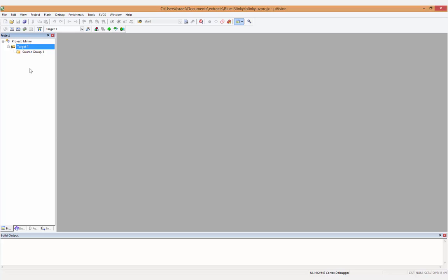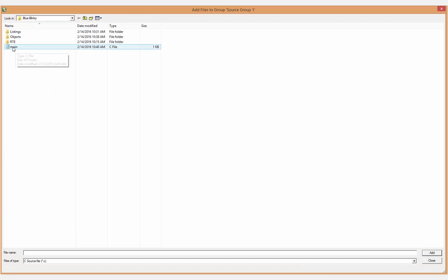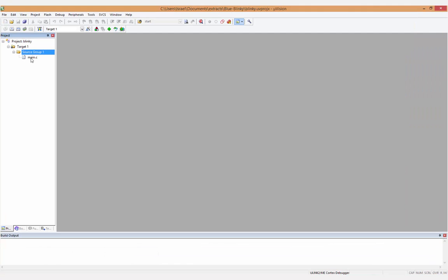And sometimes when you open an already made program, you need to set up the board again. And because of that, we're missing some of the files here. So first of all, let's import our file. The files are in the same project folder, just that they did not get imported with the project. This is very easy. Let's double click here, and this is the main file, the program main. So let's double click, it's imported, and then we click close. You can see it here, it's now here, main.c.